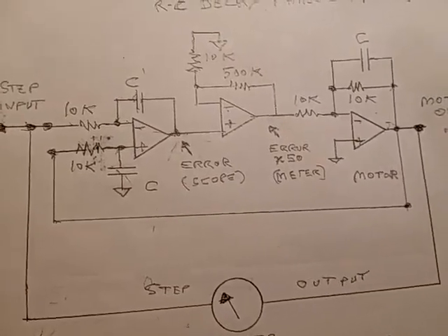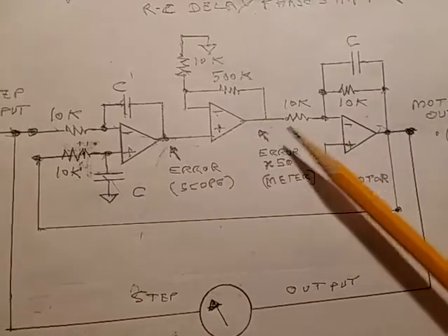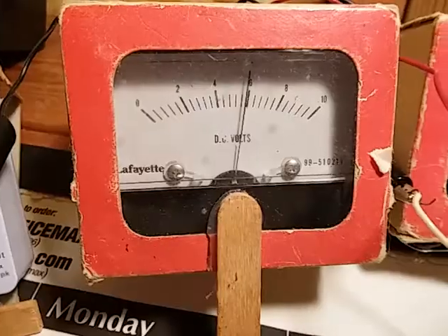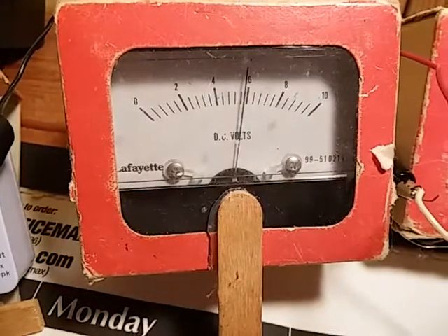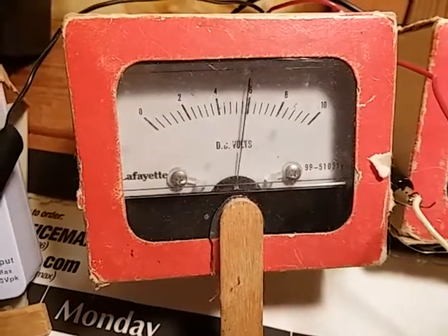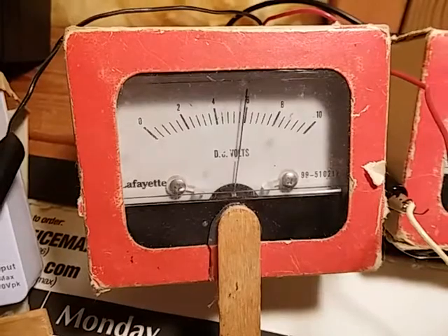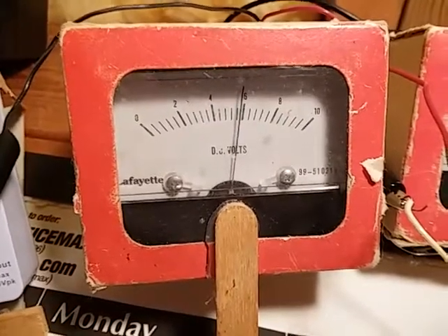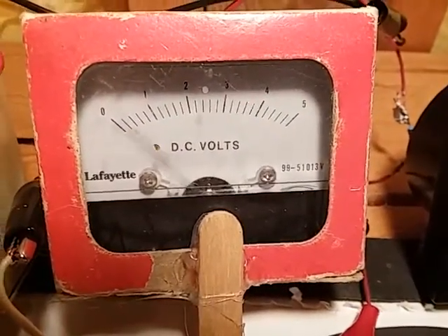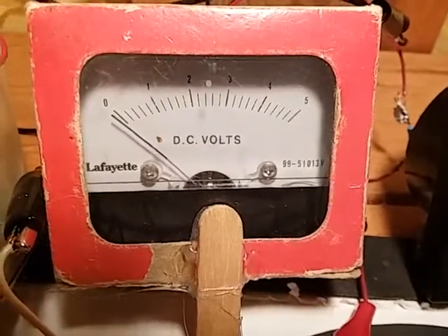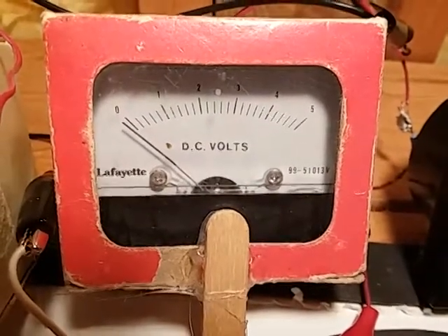So now I'll show the error signals on the meters, starting with the error signal, error times 50, and then the output. Here's the error signal. Now the error signal will be about off by 0.15 volts. There you might be able to see it. And here's the error signal multiplied by 50. Notice the sudden pulse going all the way to 7 volts, 15 volts. And the pulse in the opposite direction, same thing.